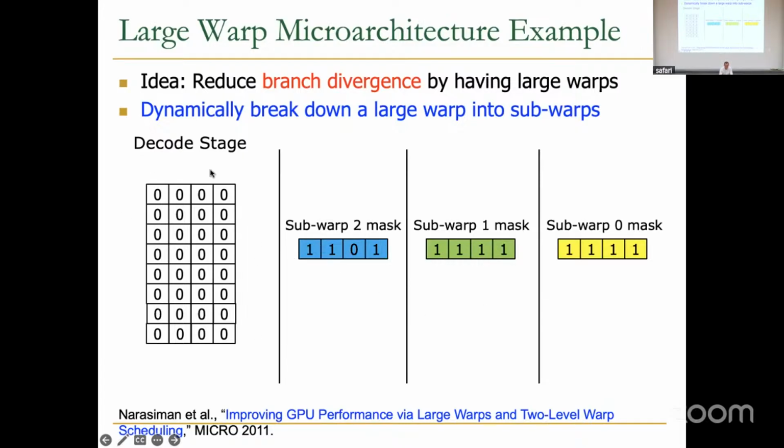So you can see that if you have a bigger picture of which threads are at which location, this is assuming that all of them are at the same program counter, of course, you can utilize your pipeline nicely with a lot of active threads in different warps. There's only one slot that's wasted over here because you don't have enough, let's say, threads that are executing at that lane.